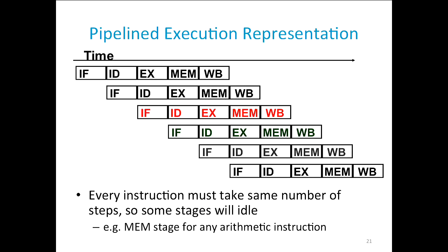So one reason this pipelining works is that the instructions are designed so they all go down the same set of stages. In some cases, they won't use anything in a stage, but by making them all look the same, it makes it a lot easier to build this pipeline.